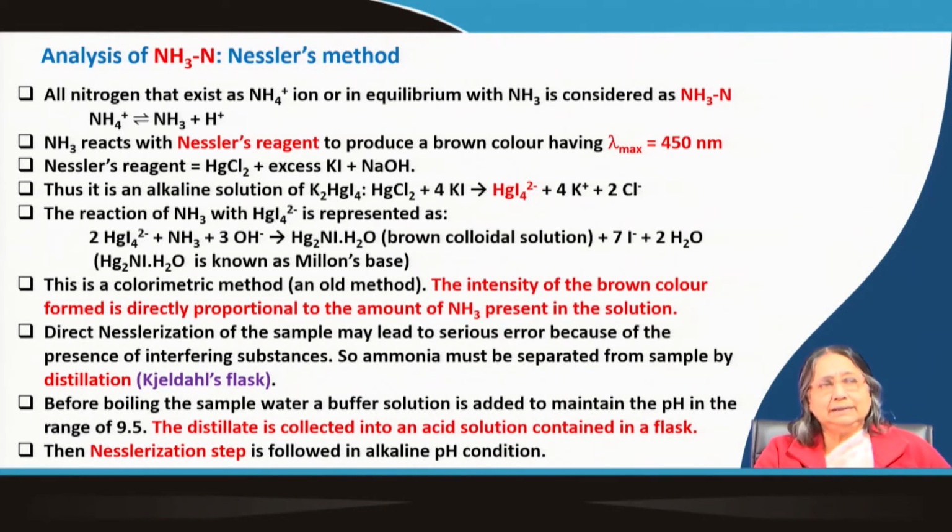Now, after it is collected there, two things you can do. One thing is you can take the sample from there, say for example 100 milliliter you are taking, and then you have to put the Nessler's reagent there.